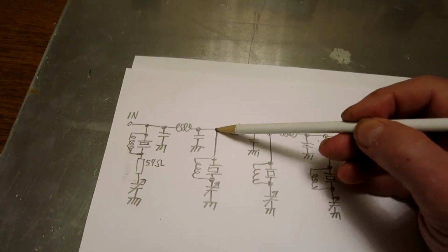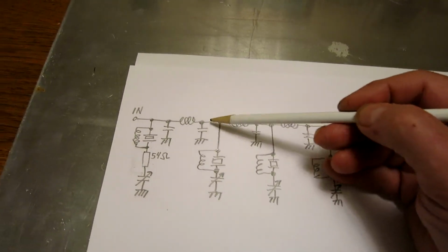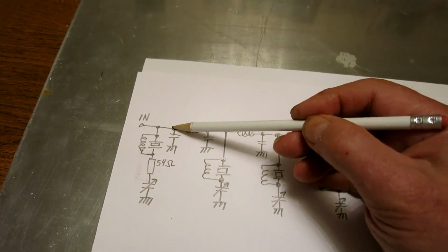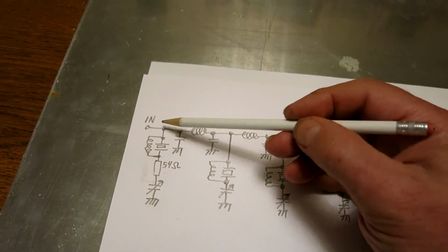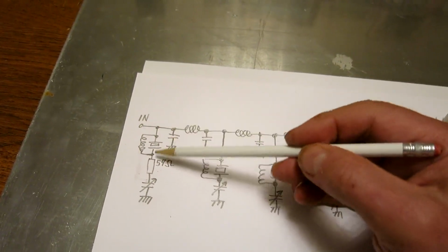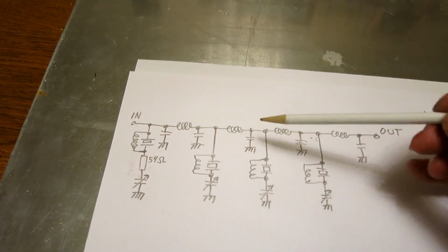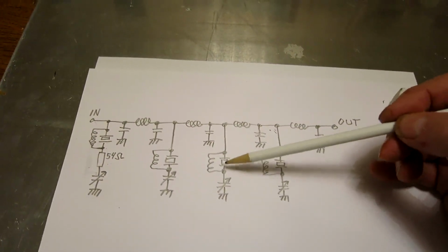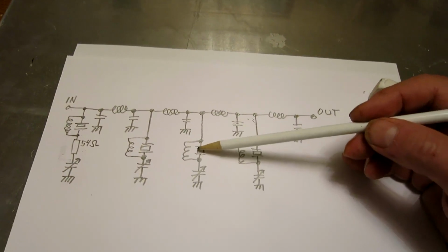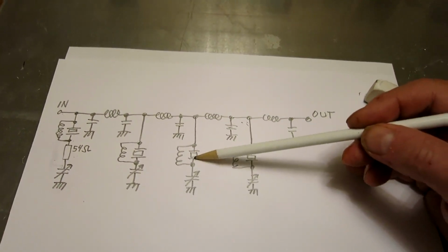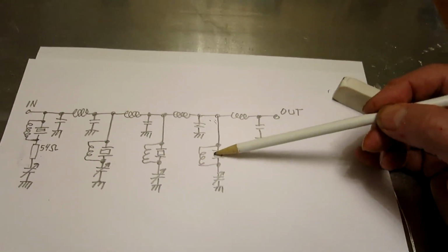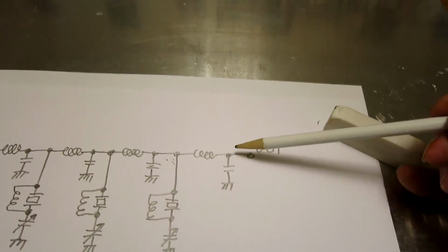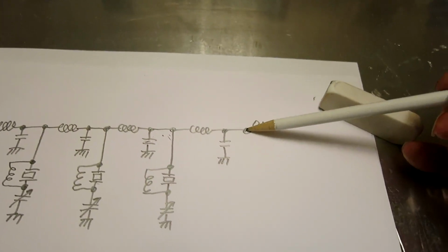Presents a very low impedance here, means that from this transmission line the impedance is very high on the notch. So on the notch the only thing that is visible is this resistor. And then there are transmission lines and more notches. Now the level is low, so there's only one or maybe two crystals here, and then there is still another one, and then there is a final link to fine-tune the impedance, because I want 50 ohms and a very low loss through this.